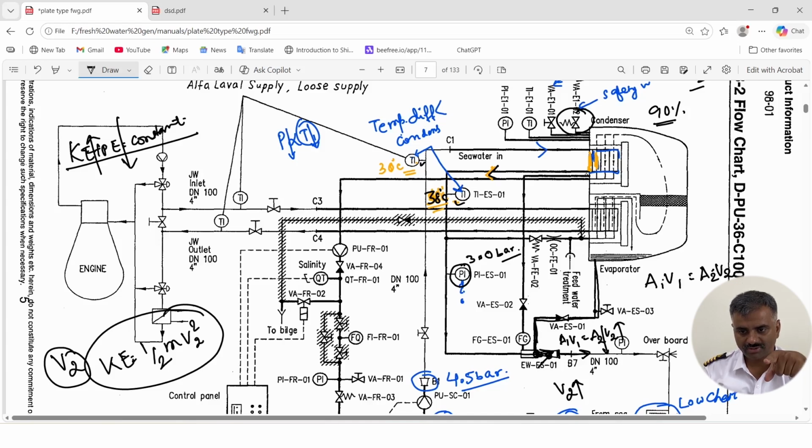And also one important line is here. This is the line called the air ejection line, and from this air ejection line air is drawn inside the ejector. This is a non-return valve, and through this non-return valve air will come inside the ejector, due to which your condenser will always be in vacuum.